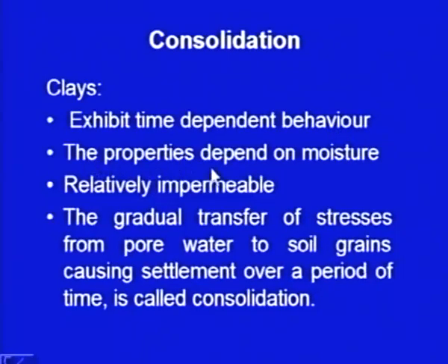Secondly, the properties depend on the moisture content. So, water is very important, the moisture is very important as far as clays are concerned. Third point about these soils is that they are relatively impermeable. So, if you apply load on the soil mass which is having predominantly clay soil, then water will not squeeze out very easily, it will take time, they are not permeable, and this will create problems. This is the reason why they show the time dependent behavior.